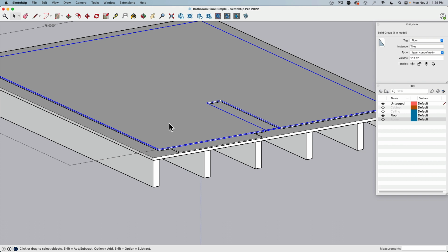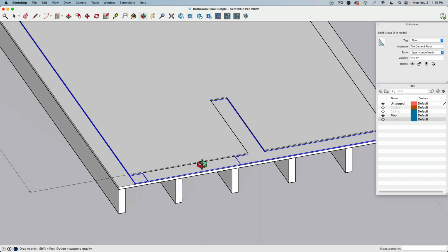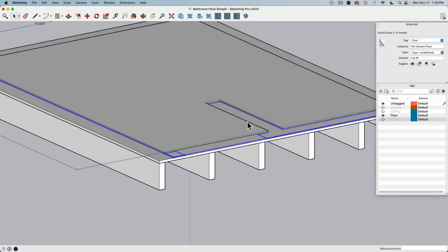Now tiles can break, they're very stiff, which is why we can't put tiles directly on a subfloor, which is made out of wood. I mean, technically speaking, you can, it's just not advisable. So we have to stiffen up the ground under the tiles. And that is the reason why between the tiles and the subfloor is another 1/4 inch layer of geometry, and that represents actually a concrete mesh reinforced construction. This can be poured, this can be bought in sheets and put down, and essentially it stiffens up the ground under the tiles.